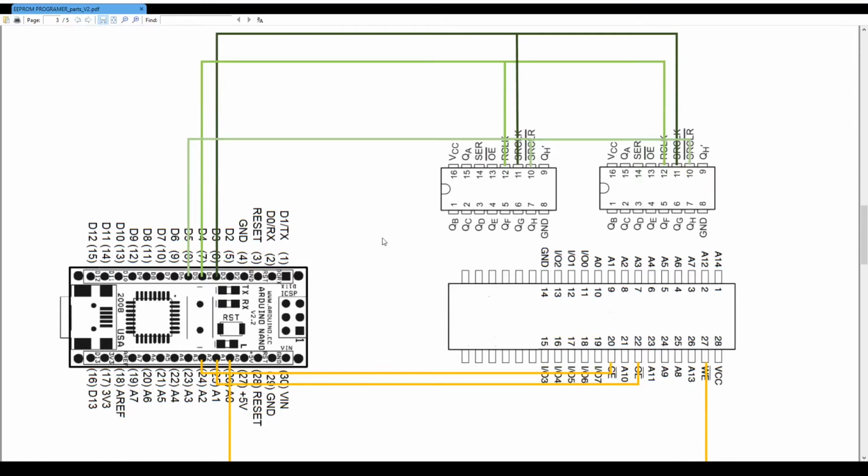And this part of the schematic shows the controls we'll have to use to be able to work with the shift registers. We have not only the serial data coming from pin 2 that I showed, we also have the clocks, and it uses 2 different clock pulses. One of the clocks, which comes from pin 3, is the SR clock, and this one should pulse for every change in the serial data. It will then shift the bits inside the register.